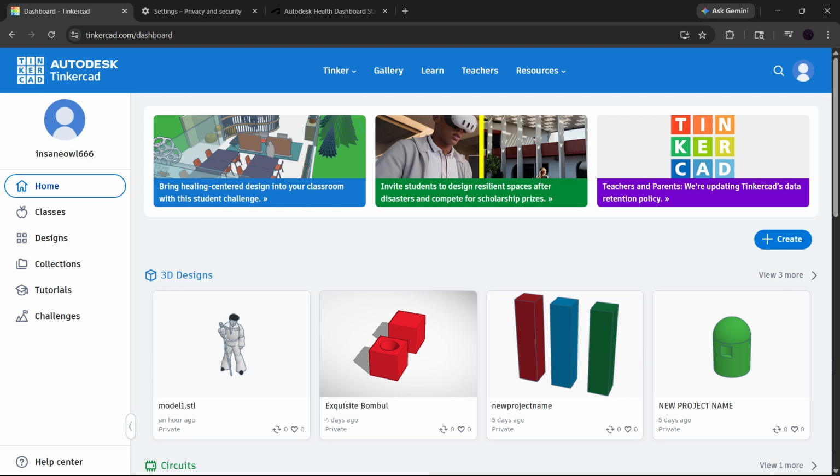So to recap, hard refresh the page, wait a minute, enable hardware acceleration, clear your cache and cookies, test in Incognito mode, check your circuit logic and code, and verify Autodesk server status. In most cases, one of these steps will solve the Tinkercad error has occurred message quickly.